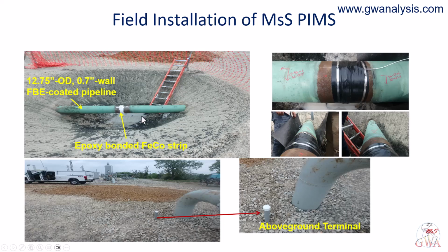A bonded epoxy coating is thin and tightly attached, and on such lines we measured a longer inspection range at high frequency than at low frequency, which is the opposite of the usual expectation for a coated buried pipeline. Note also the wall thickness: 0.7 inch on a 12.75-inch line is a heavy wall. That is a line worth monitoring rather than replacing,